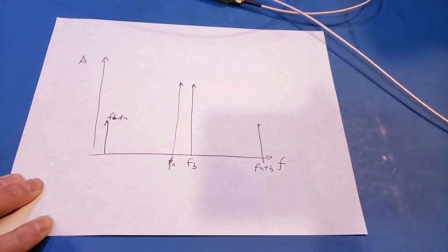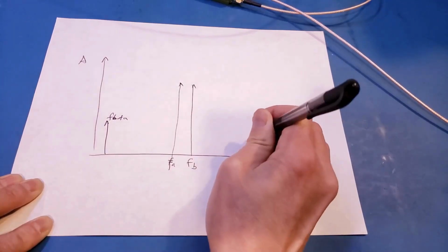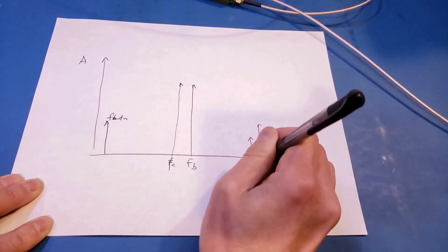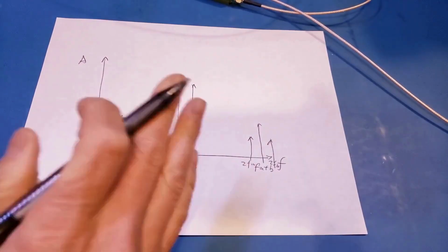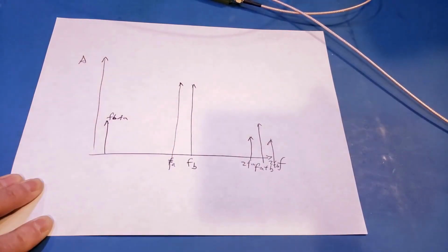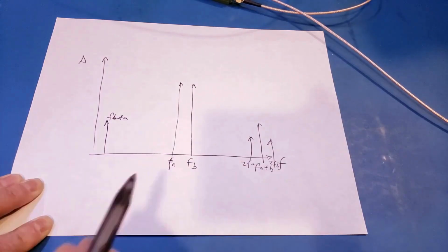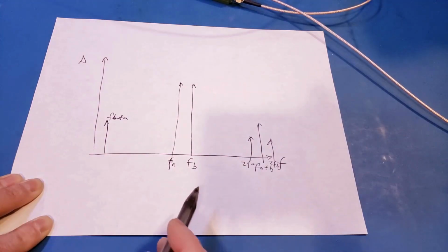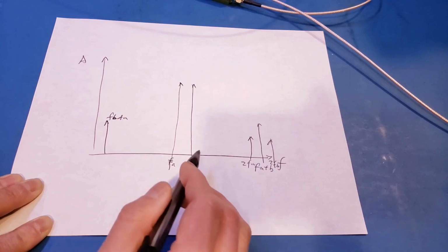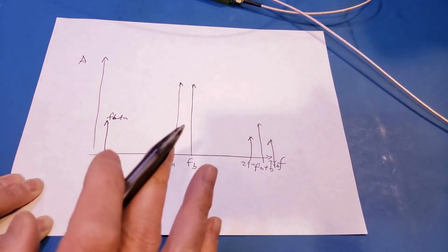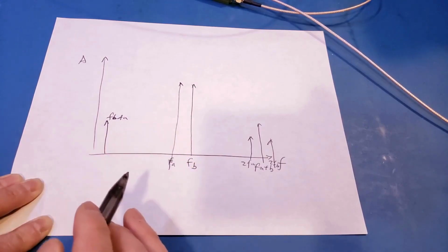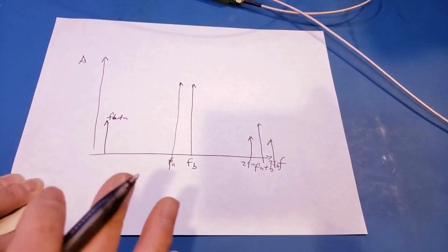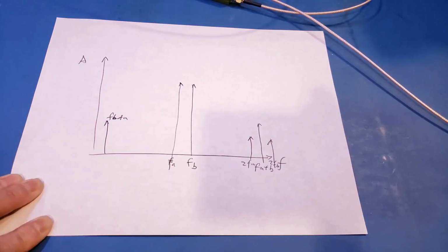Of course, you also have the harmonics, for example, the 2 FA here, and 2 FB. So these are some of the frequency components. And what I have shown you here, these are the second-order intermodulation. Now, when the original 2 fundamental frequencies, FA and FB, are close together, like what I have shown you here, the frequencies of these second-order products are pretty far from the original frequencies, so they rarely cause any problems, as they can be easily filtered out.